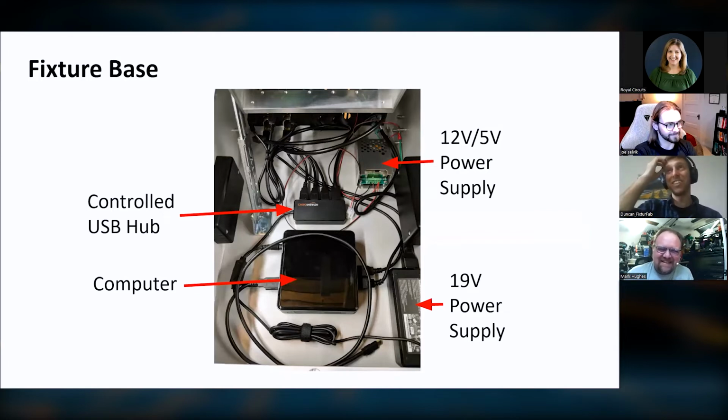Yeah, I mean, it's hard enough to just measure a clock signal. Our go-to way to do that is have it get output via an IO pin that's not being used on a processor. It's way easier to measure that than trying to probe a clock signal on an actual circuit board. Yeah, you could have publicly shamed me on that one. It would have been okay.